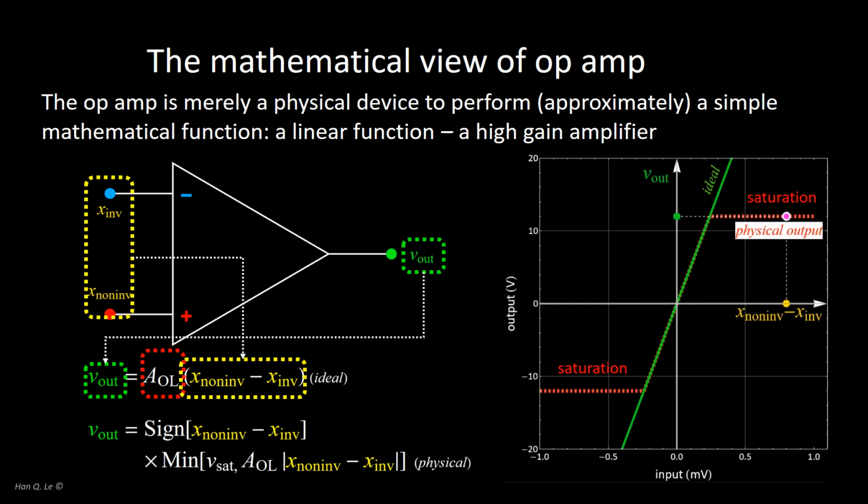How can such small voltages be controlled? There is a method to do that, which is negative feedback, and precisely the reason the op-amp is designed with such a high gain is because it is not intended to be used as is, but only with negative feedback, which will be considered next.